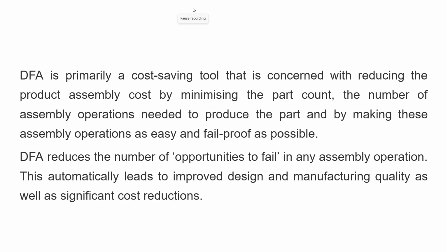The number of assembly operations needs to be reduced by reducing the parts, and these assembly operations should be as easy and fail-proof as possible. DFA, design for assembly, reduces the number of opportunities to fail in any assembly operation. This automatically leads to improved design and manufacturing quality as well as significant cost reduction.